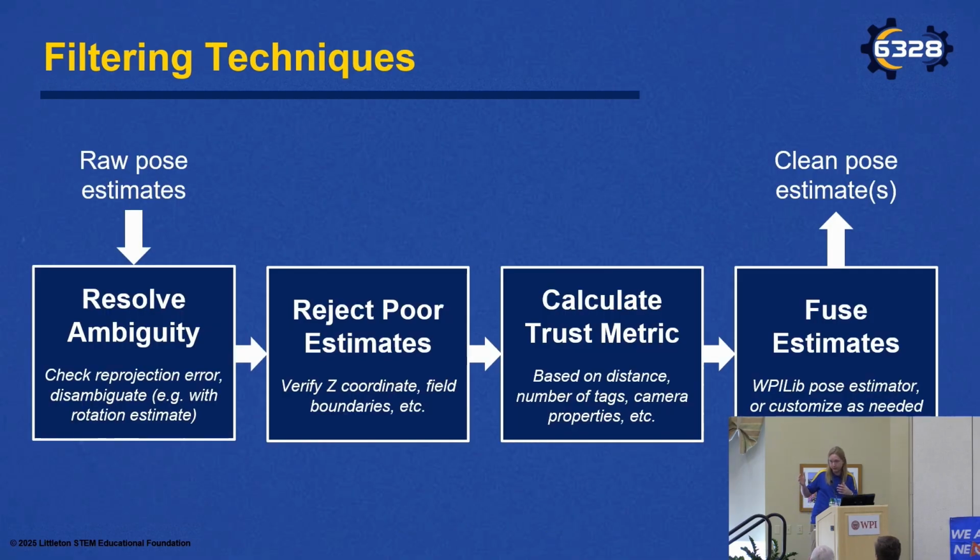Okay, now regardless of the solver you choose, as I said, they all have noise, which means that global positioning always requires good filtering. You can sometimes get away without that with local positioning because you're dealing with a very constrained environment, but global positioning involves multiple cameras, tags at a variety of distances, and multiple kinds of error. You may, from time to time, run into template code that uses vision for global positioning but doesn't properly account for filtering. Generally, as a rule of thumb, you should be suspicious of anyone saying that filtering is unnecessary or an afterthought. It's absolutely critical for global positioning, regardless of the algorithm you choose.